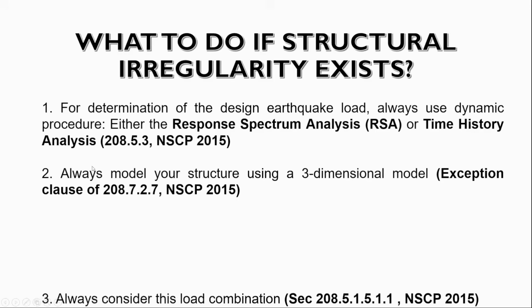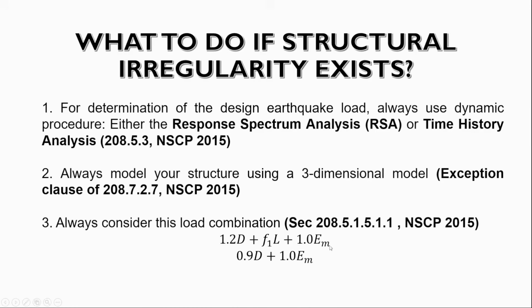Then finally, we should also consider this load combination. That is the correct way of dealing with irregularity. Irregularities in a structure are not forbidden except the extreme weak stories. And any plans or designs by the architect can be designed well, can be safe and have a good structural design.